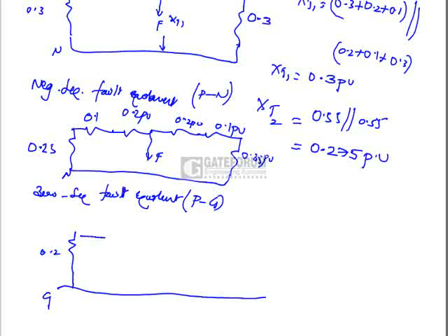Okay, after that we have delta. Delta means shunt connection, so primary is delta circuit, so we have to operate shunt switches. Okay, transformer reactance is 0.1 per unit. Okay, after that secondary is star grounded, so we can operate the series switch here since it is grounded.